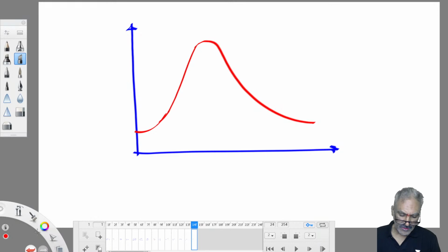For some other storm you can't apply it. That means storm to storm, the storm hydrographs or flood hydrographs vary. For every storm you have to measure. Therefore, that storm information we also mention in the hydrograph, as a plot of intensity of rainfall versus time.